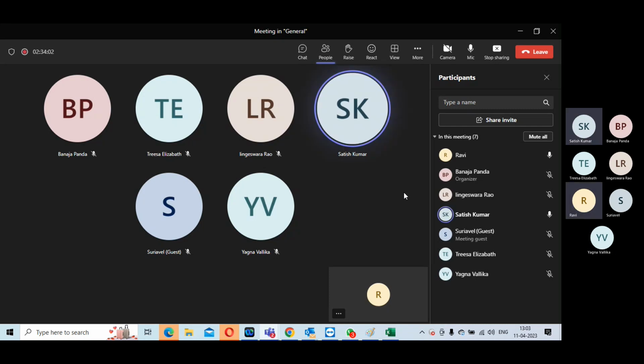Like the spacing between macros, and between the macro block edge and your circuit row, what it should be, what should be the height. All these rules, at least right now I won't talk about them, because if I talk, then we will just get stuck here. So then check library, check timing, and check design; all this should be clean before you exit your floor plan.